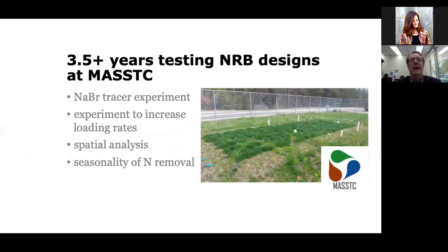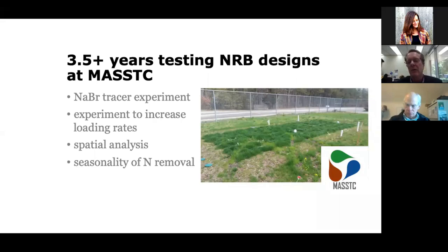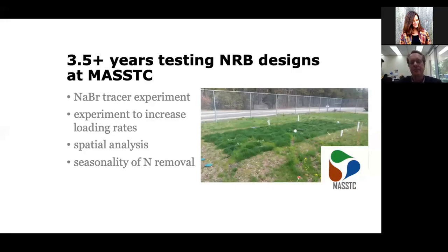So, 3.5 years of testing NRB designs at MASDIC. That has involved a lot of research and a lot of monitoring, and I'll talk about 3 different parts of that today. I thought we could talk just about that for the entire hour. So we did a tracer experiment to find out the residence time of the sand bed, that is how long the wastewater stays in the sand bed, and how long it stays in the unlined biofilter.